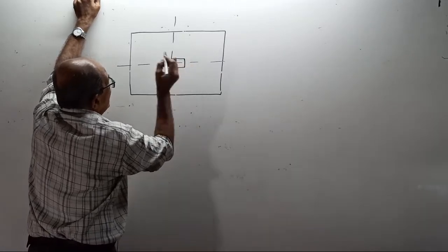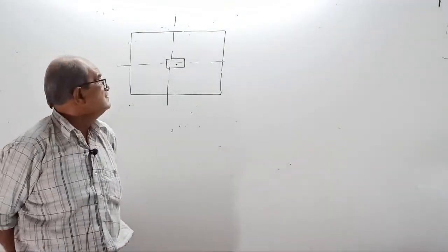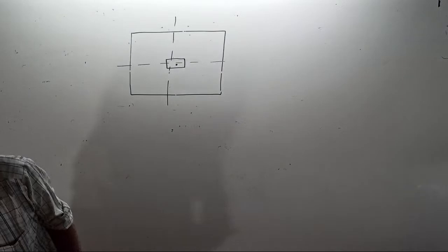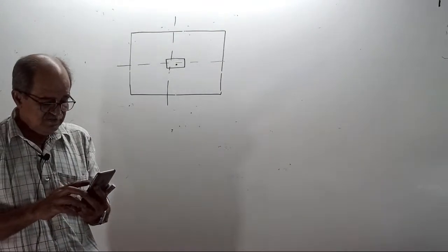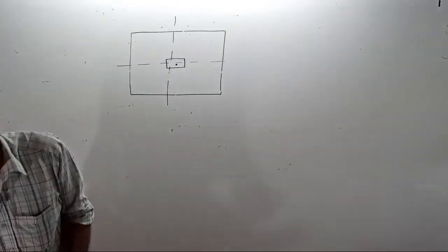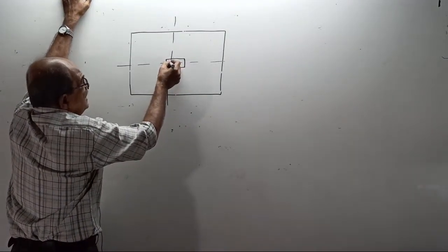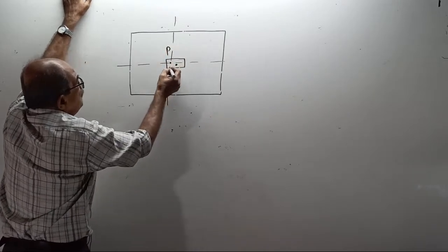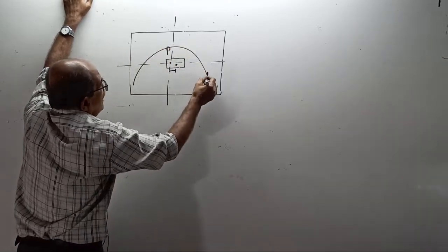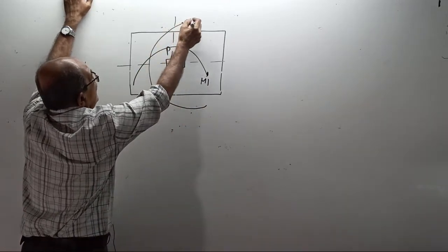So the column center is here. This is called what? Concentric or eccentric. First, this is concentric. This is called eccentric. If it is eccentric, the load is acting here. When you consider the CG here, it will give a load P. Because of this eccentricity, it will give a moment this way, M1. And because of this eccentricity, it will give one more bending moment here, M2.